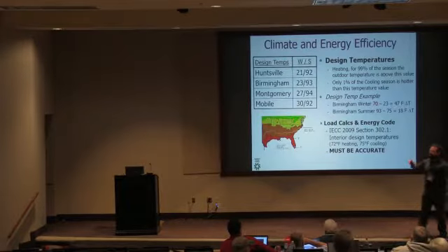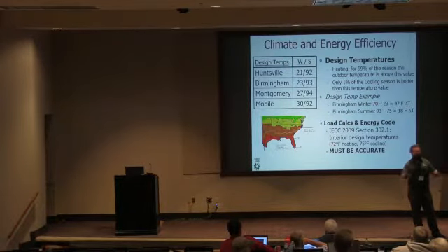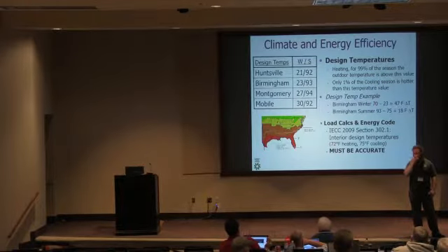I actually have a slide coming up in a minute. This is really interesting. When you spray foam a roof line, you bring down the balance temperature at which the heat pump can operate. So your heat pump can make hot air at colder outside temperatures in a spray foam roof line house. And I'll go into that. Obviously, if you spray the roof line, you're going to have to spray the gable wall as well in order to create the membrane.